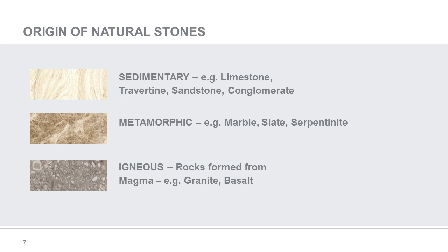Slate may be riven. Riven slate tends to vary in thickness, and within all uncalibrated stone, the variety in thickness requires consideration for the installation and leveling products required. Some sources of slate may contain oil, which can lead to the initial adhesion being lost as the oil migrates to the tile adhesive interface. It's always sensible to trowel a small area first. Honed stones are machined to create a smooth and even surface.